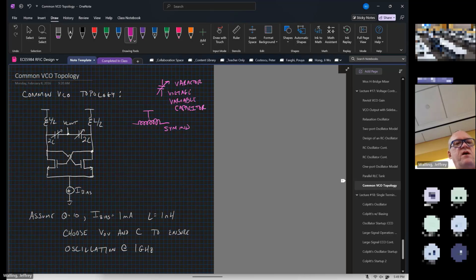All right, it's important to note that the reason that we have L/2 and 2C is that the passive components are in series with one another relative to the virtual ground that's in the center. And so that's why I've doubled the value of the capacitor. 2C in series with 2C is equal to C. And the value of the inductor L/2 plus L/2 is equal to L.